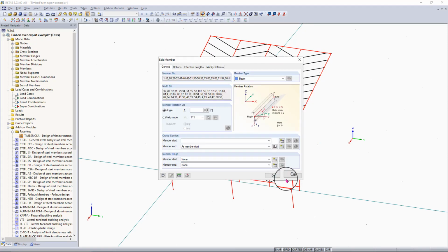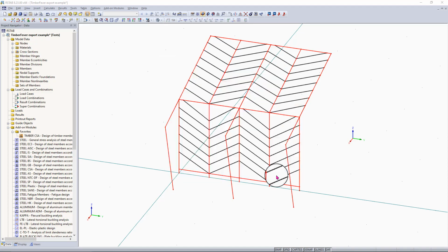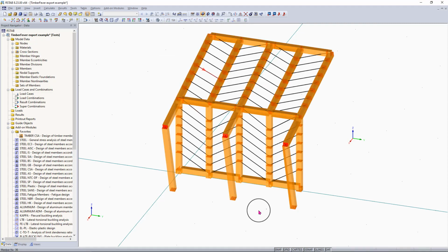and then we'll click OK again. And you can see that now we have our cross section and we have our material defined for that cross section. So we can click OK. And now we have all of our posts defined, our cross sections and materials. One thing I would like to mention before we move on is that timber, every connection should have a moment release. There can be no moments taken by the end and start of the members here at the connections.